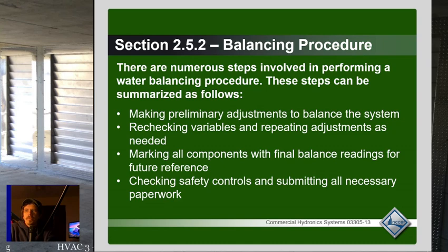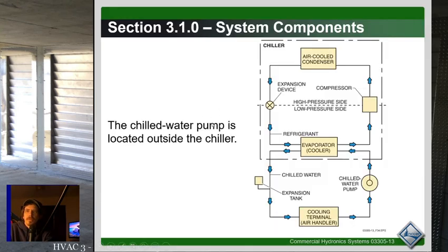Marking all components with final balance readings for future reference, checking safety controls, and submitting all necessary paperwork.